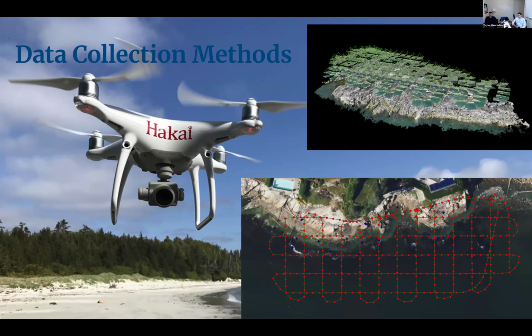We'll use ground surveys where we can. So this example is part of a Marine Multi-Agency Rocky Intertidal Network site that we set up last year in West Vancouver. And so we were out with RTK GPS and ground control points. So we have really accurate heights, and we convert that to chart datum. In areas that we can't get to, some of our more remote rocks, we use the tidal height and adjust based on that. And then we can take measurements in the data.